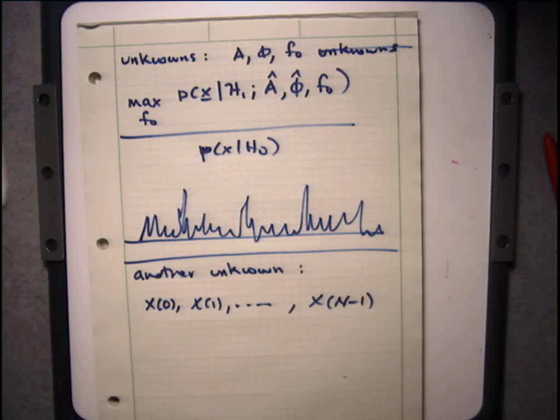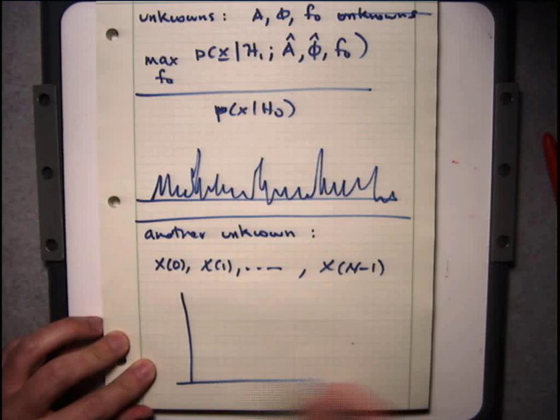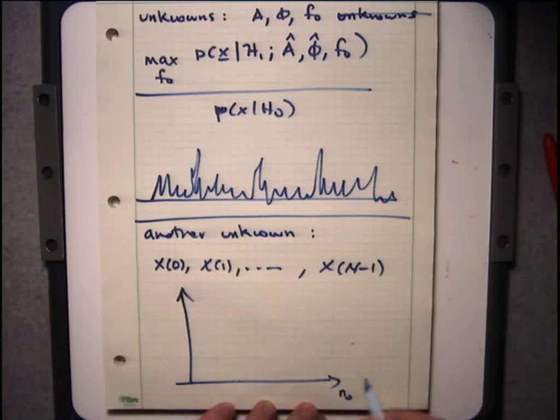Well, what you have to do is exactly what we just talked about here in a windowed fashion. Okay? So you don't take the entire 100,000 and do a Fourier transform on it. What you do is you take a window of, let's say, 10,000 samples, and you slide that window across your 100,000 samples, or you just do this on an ongoing basis online, and you plot something that basically does the following. It assumes this n0 is, so let's say this is the start time.